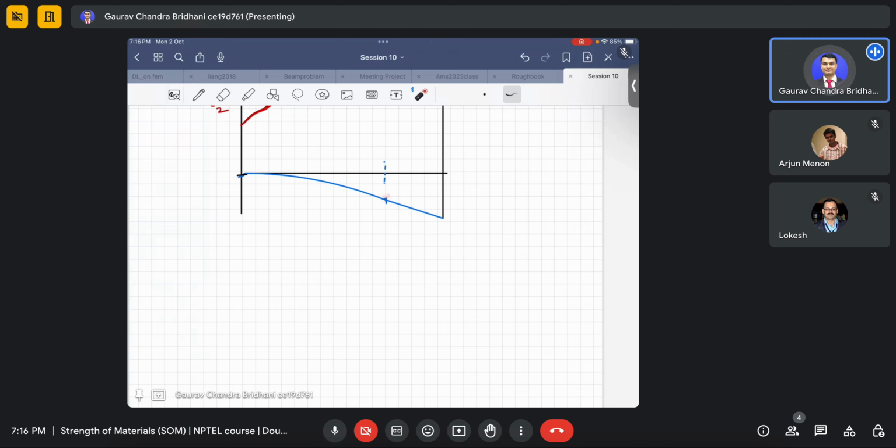So we can do that, but to come at this Q, which is also our point of interest, how to come up with the deflection and the theta here? What we do is actually find theta here first of all. We draw a horizontal line here, and the line extending beyond this point is actually a tangent at this point itself to the elastic curve. As I told, this will become a straight line, so this line acts as a tangent to this curve at this point. Hence we found the theta, which is the slope.